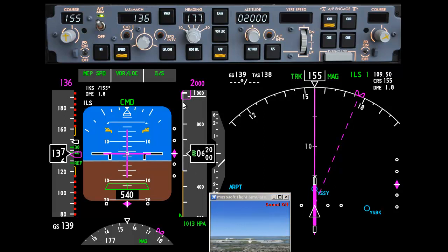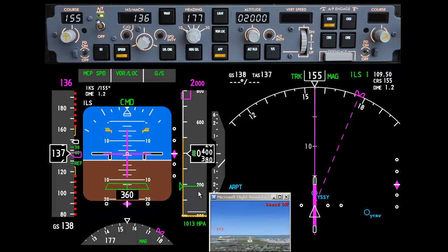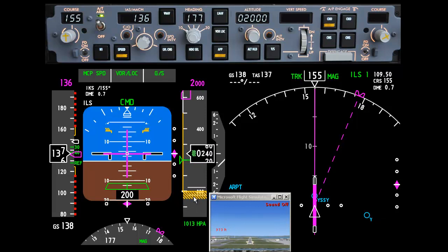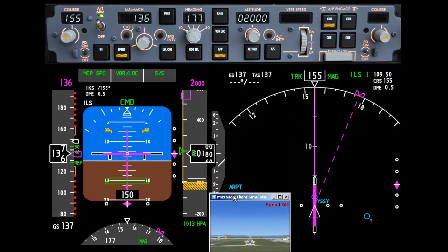ground. Over here, we have a white line at 1,000 feet indicating 1,000 feet above the runway. This yellow bar indicates 500 feet above the runway, and this green bar indicates the decision height. I can alter that, and we're going to say 200 feet in bad weather. That's what we actually need to look at. This yellow marking down here indicates the elevation of the runway. At the moment it's sitting at 0. Sydney's 21, but I haven't programmed that into the flight management computer yet.